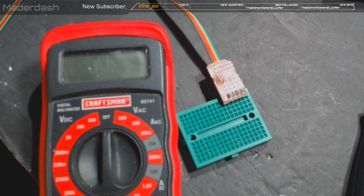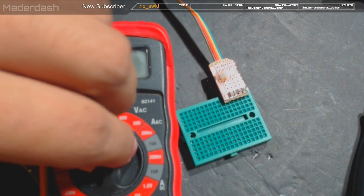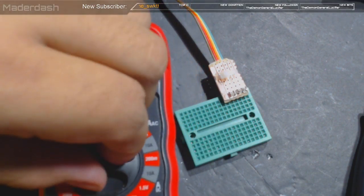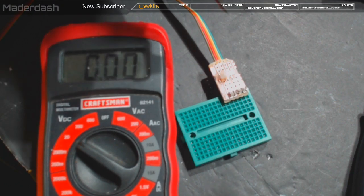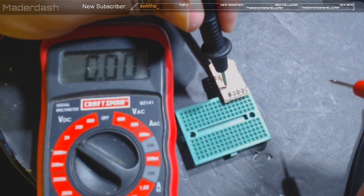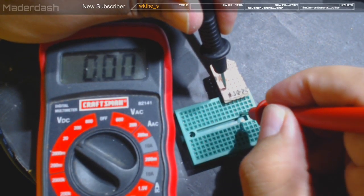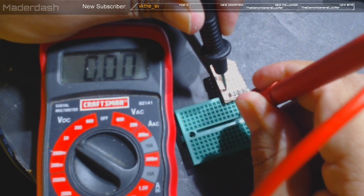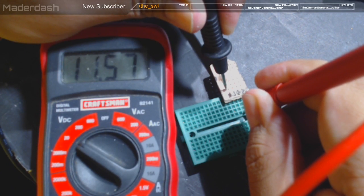So if I got this right, we should have ground on the brown wire, which would be this one. I'm just going to touch this circuit here. Then we should have nothing. There we go. There's 11 volts.